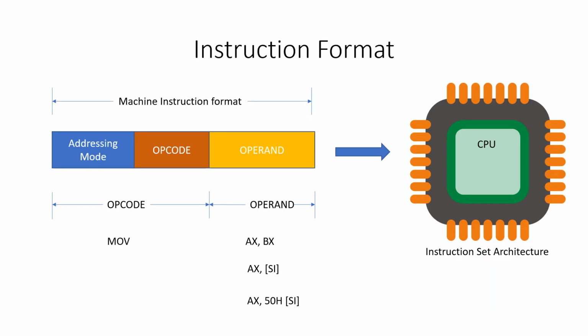To mention the instruction format, we have a structure with an opcode and operand, and there is also something referred to as addressing modes over here. Before venturing into addressing modes, we'll understand what an opcode and an operand are. Opcode, also referred to as operational code, we can indirectly point to as mnemonics also. The operational code is all about what kind of execution is going to happen.